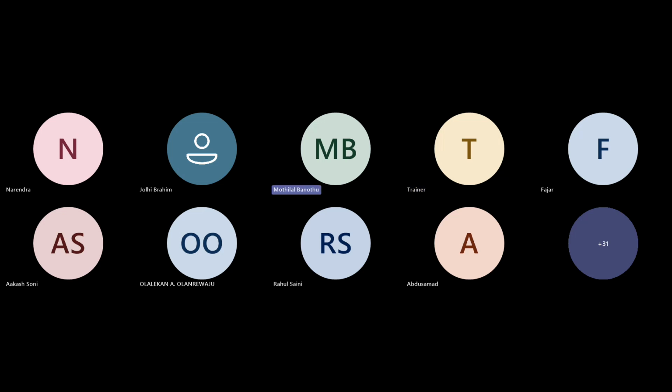In the beginning, before the pre-design, we need to provide a scope of work. In that, we need to mention this particle size diameter, right? Yes, if you require it in any particular situation. Generally, people use the K value, which does not take any diameter consideration in separators. But generally, people define how much liquid carry over along with per MMSCF of gas, like 7 lb per MMSCF of gas, or 150 ppm of liquid carry over, something like that.